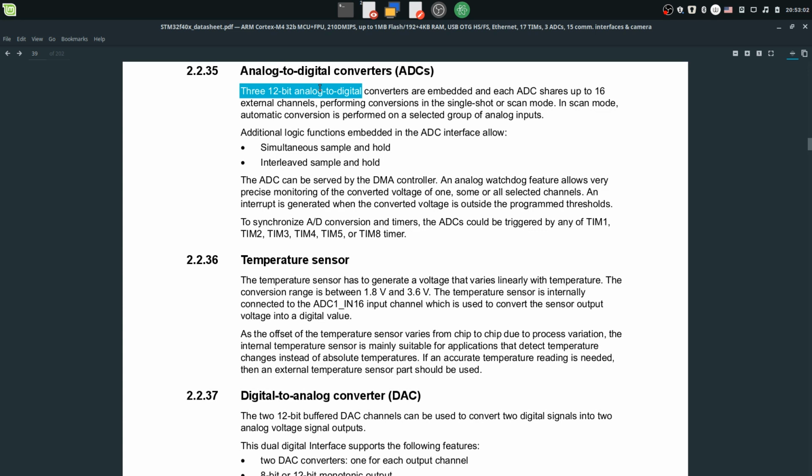That's because each ADC has a multiplexer, so it can select from which pin it is reading. That way, if we multiplex through multiple pins at very fast speed, we can pretend that we're reading from multiple pins at once, but by reading one after another in a controlled sequence and then knowing which reading is for which pin.